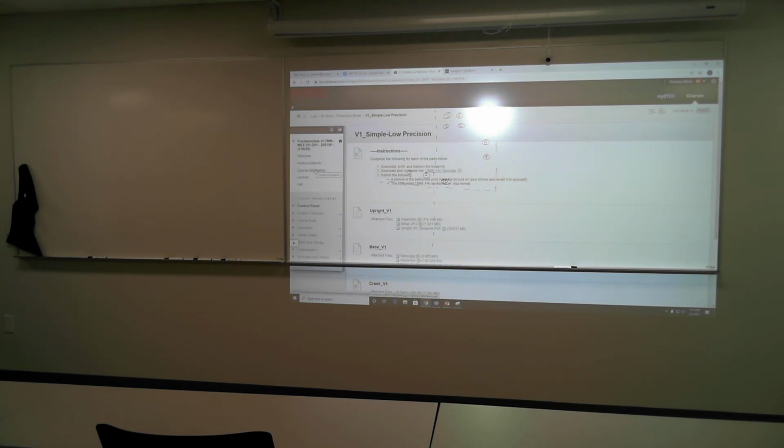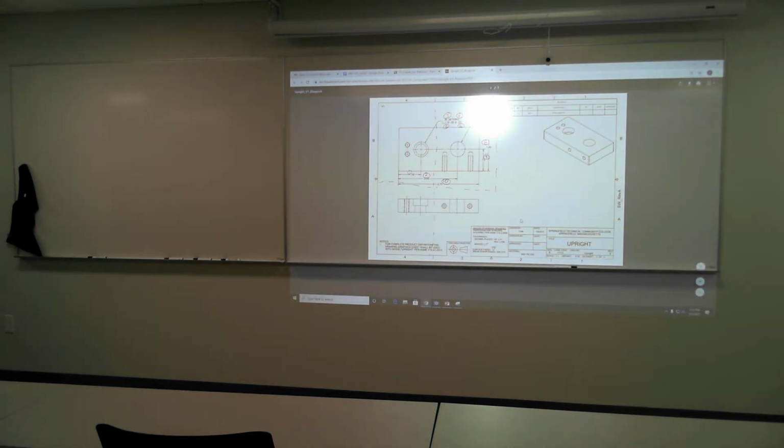So, for example, on blueprint number 4, that would be that measurement because it's a through hole. Anytime I can get a counterbore, that would be a measurement. Yep, so if you have a hole, you actually have a couple of things that could be going on with that hole. Maybe it's a counterbore hole. If it is, you have the diameter of the through hole, the depth of the through hole, the diameter of the counterbore, and the depth of the counterbore, and you want to be able to itemize them in an Excel sheet separately. So the through hole would be the depth of the piece itself, right? Correct.